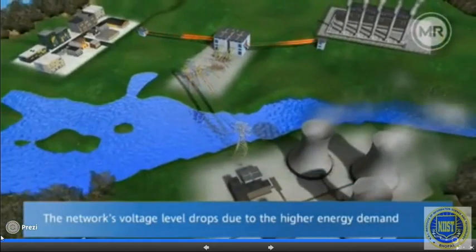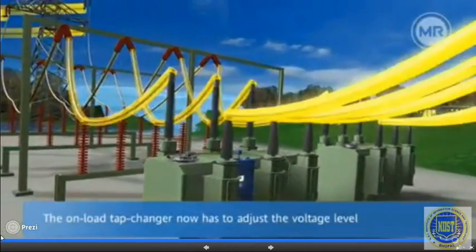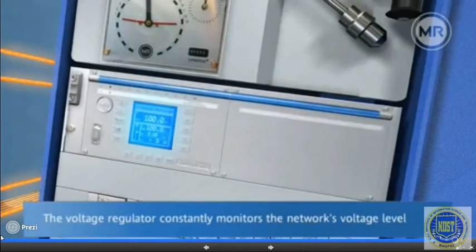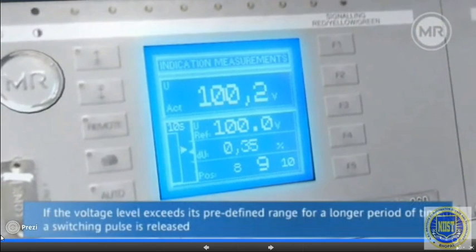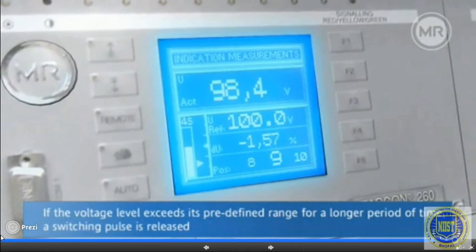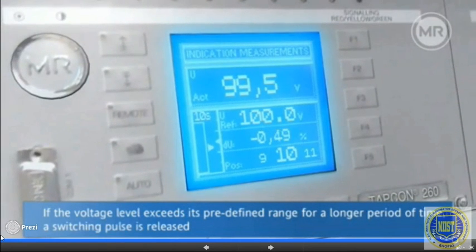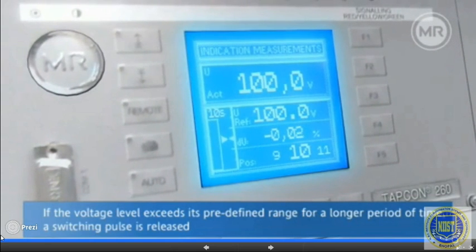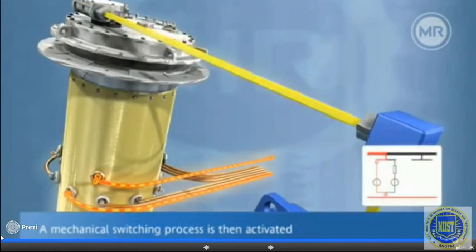Now these two load variations present a varying load pattern on the generating station during the daytime and nighttime differently, and so the transformer voltage is more likely to vary at different instants. Say if a voltage variation appears across the tap changer, then a controller senses this variation over a certain duration of time. And if this variation is not cleared, then the tap positions are changed to negotiate for the change in voltage.